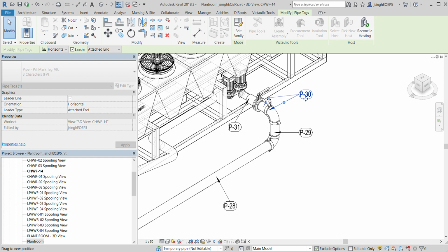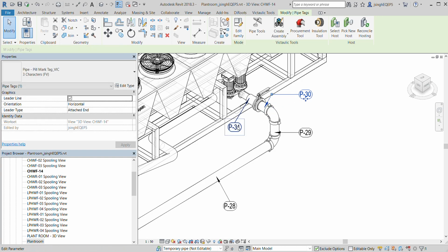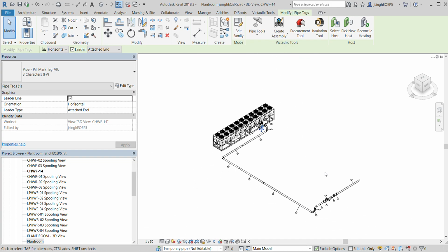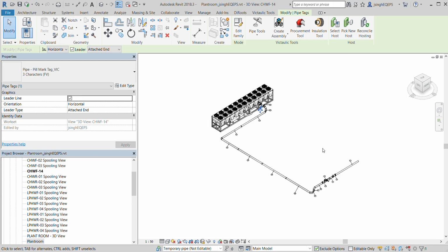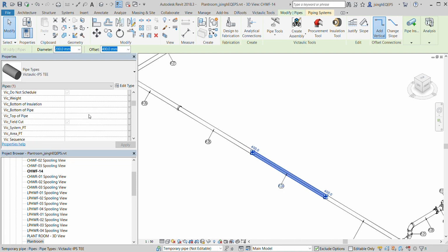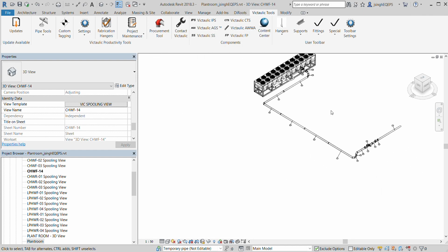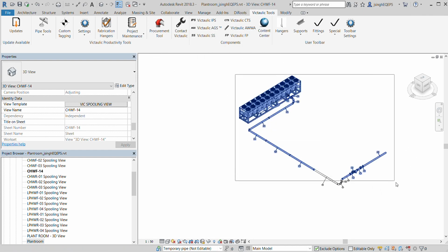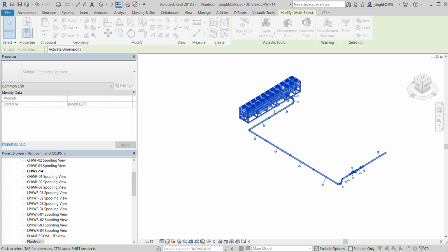So you have to make it a bit more representable. The color code is not just anything which you can pick, like whether this color represents this spool or that spool. So now if I select my pipe, it tells that this pipe is in CHW return. Okay, so when I go here, I have to select the entire thing like this, and go and filter out the pipe tags, mechanical equipment, so all related to pipes are there.